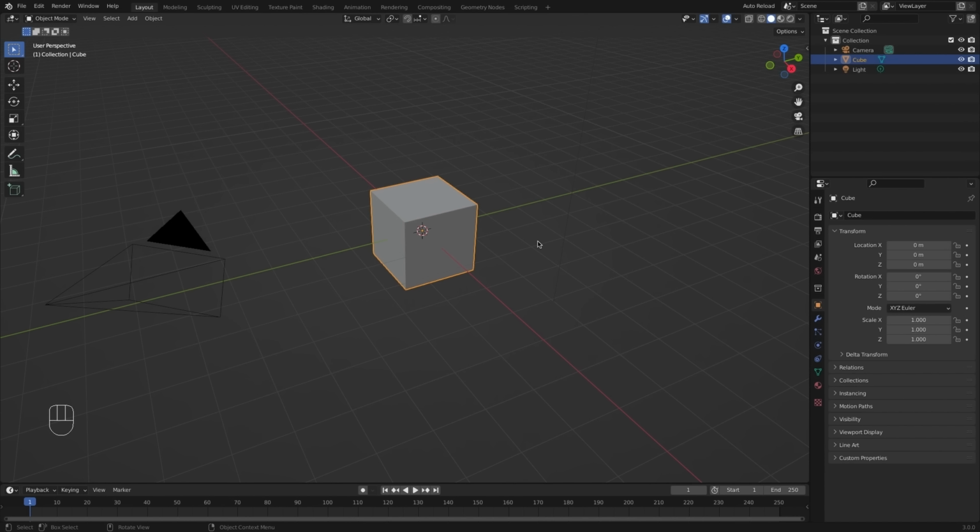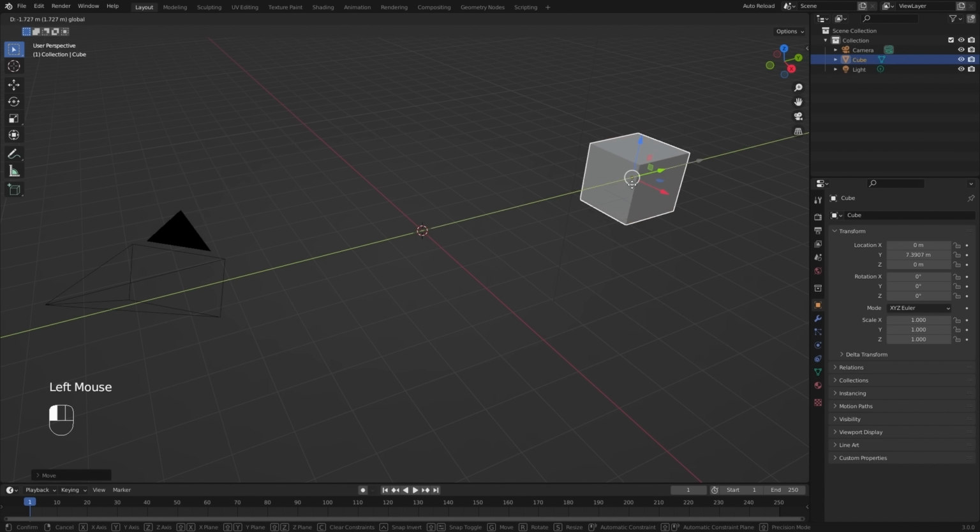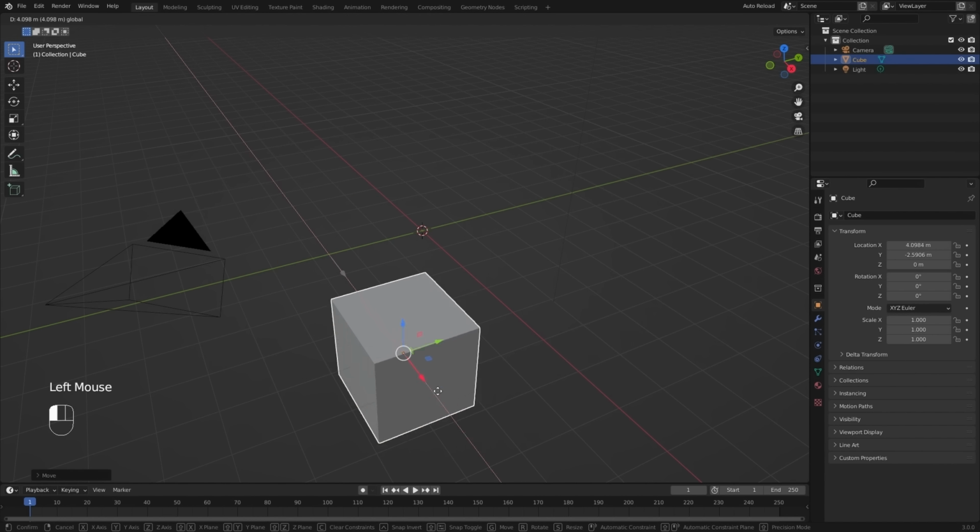I use two methods to move the objects. The first one is probably the easiest. You need to go to the gizmo menu and activate Move option. Now, after selecting an object, you can simply drag it in the direction you want, using the control arrows.